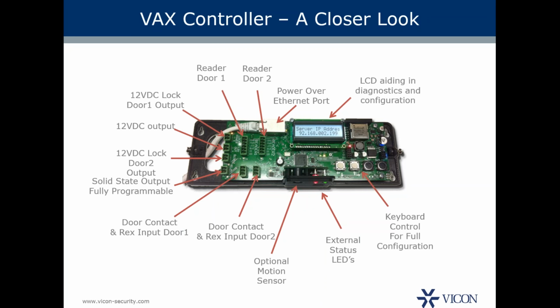We do support static and DHCP connection modes. As I mentioned, you only need one server. And something unique to this is that we have a fully distributed processing way of doing things. So the field controllers are not dependent on server operation. 50,000 events can be stored in that flash memory that's on the board.